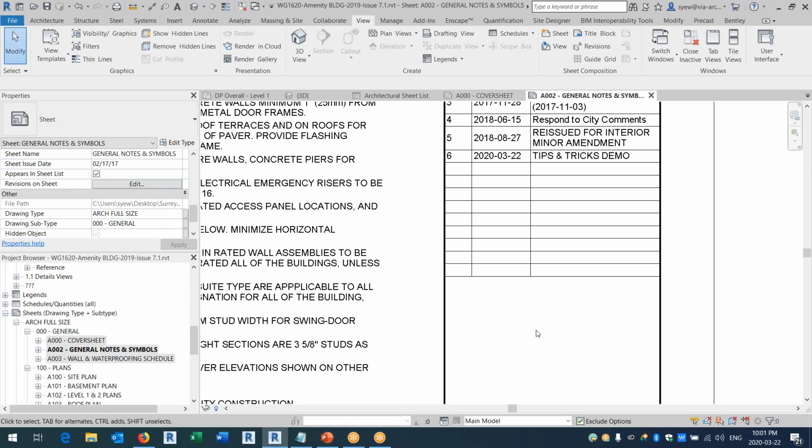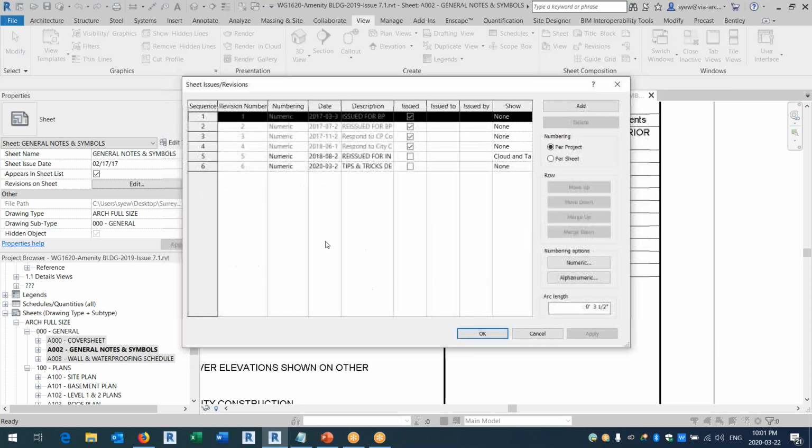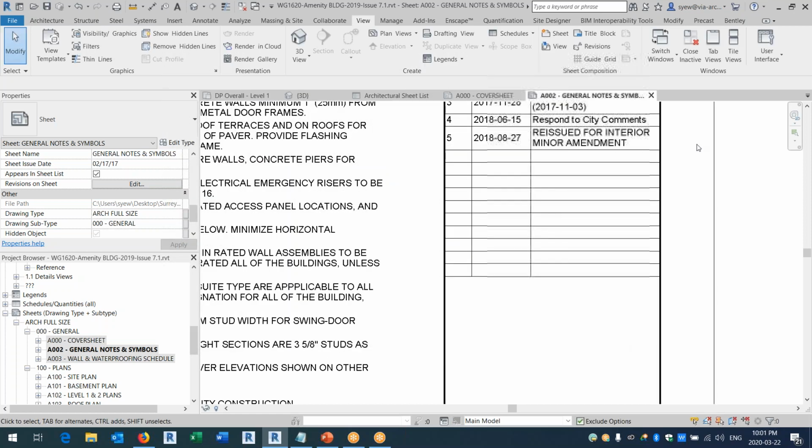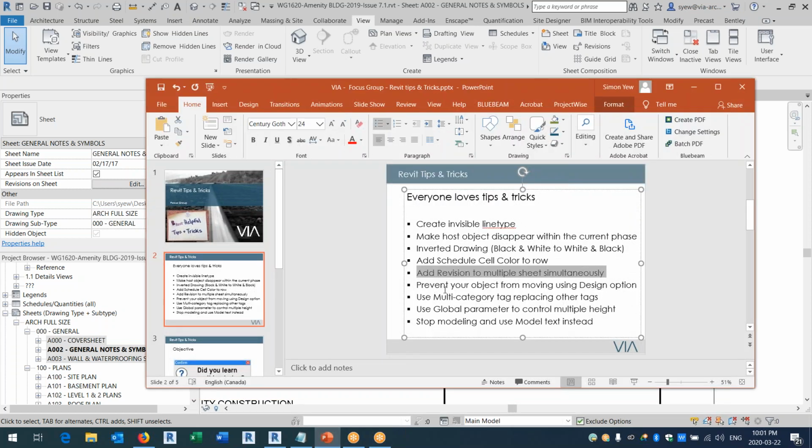So you just draw a small piece of revision cloud, and then you just copy and paste into the sheet you want. Now, if you want to get rid of it, just delete it. Okay. So that's how you delete it, let's assume that you do not need this anymore. Just hit delete, say okay, and that thing gets deleted. Right, pretty useful.